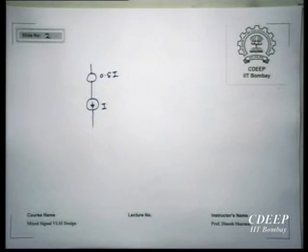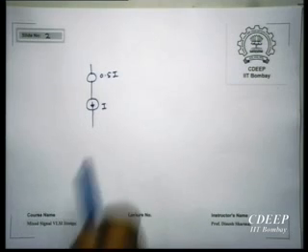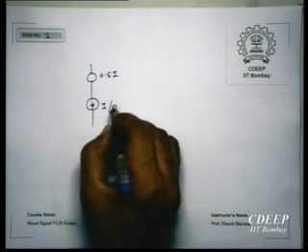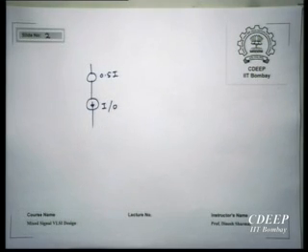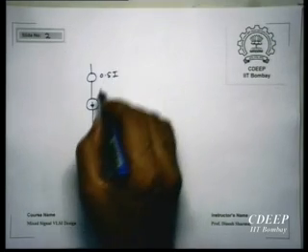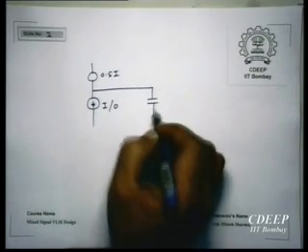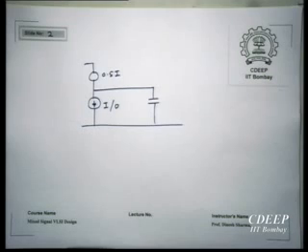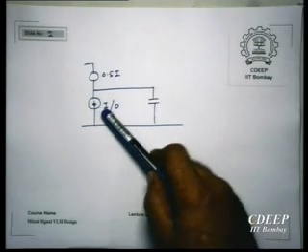Okay, so let's talk of one bit initially, not multi-bit. So this I could be 0 or I, right? So either 0 or I. Okay, and I have a capacitive load here. So this 0.5I is my reference current, locally generated, and this is the line current mirrored from that beta multiplier, which could be either 0 or I. So this being the case, when this is 0, what will happen?